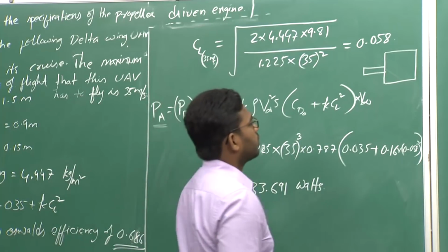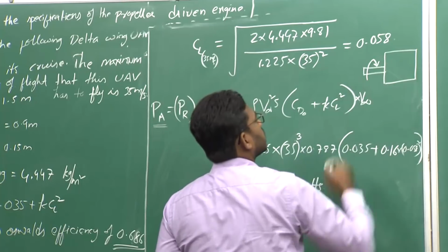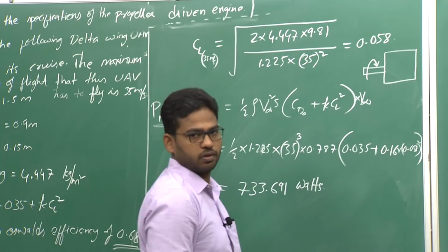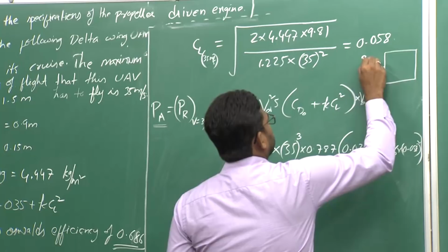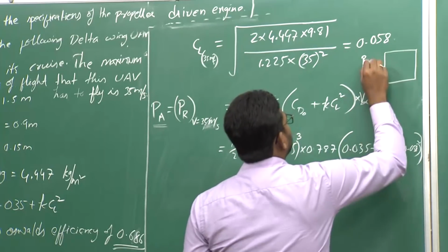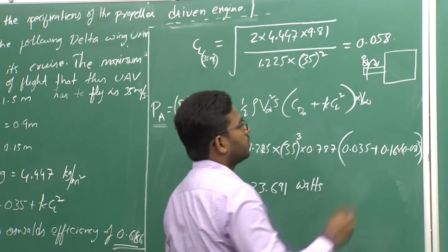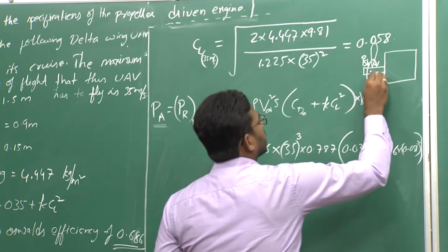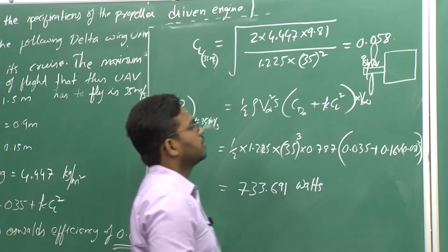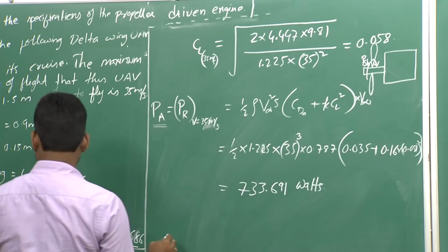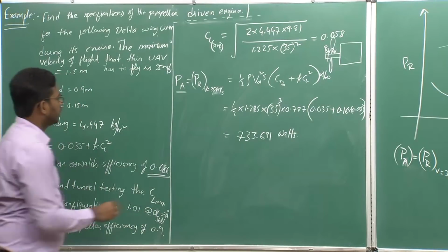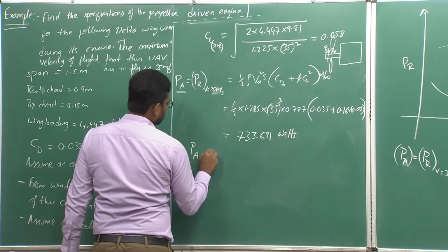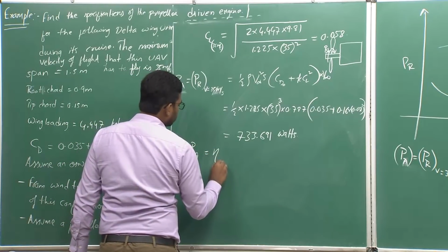But what we get as an output is a shaft power from the engine. So, the engine is rated in terms of shaft power, right. PSH is the shaft power, right. So, when the shaft is combined with a propeller, you will get the corresponding useful power, right. So, propeller efficiency is given as 0.9, and we know power available is equal to efficiency times shaft power.